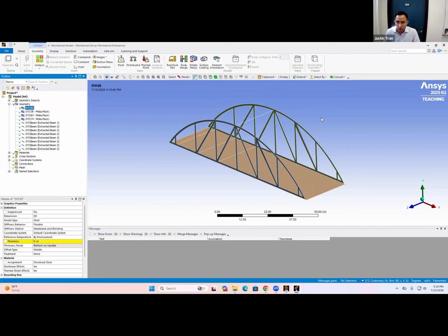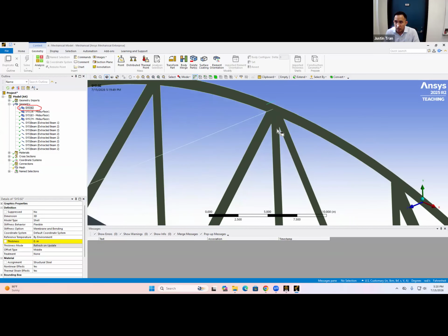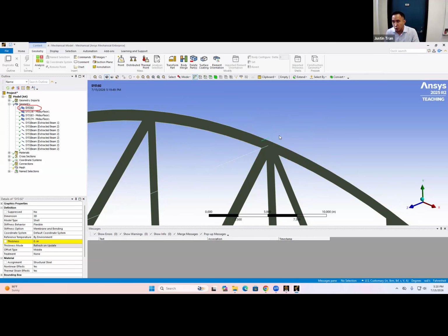First thing we're going to do is click on this part of the geometry here. It should be like SYS 92. It's the part of our geometry that has a question mark next to it. It's a little bit hard to see, but this was an extra little chopstick or toothpick that was standing on top, just a fragment from before we constructed the CAD. We don't need this for our geometry here, so we're going to go ahead and suppress this.